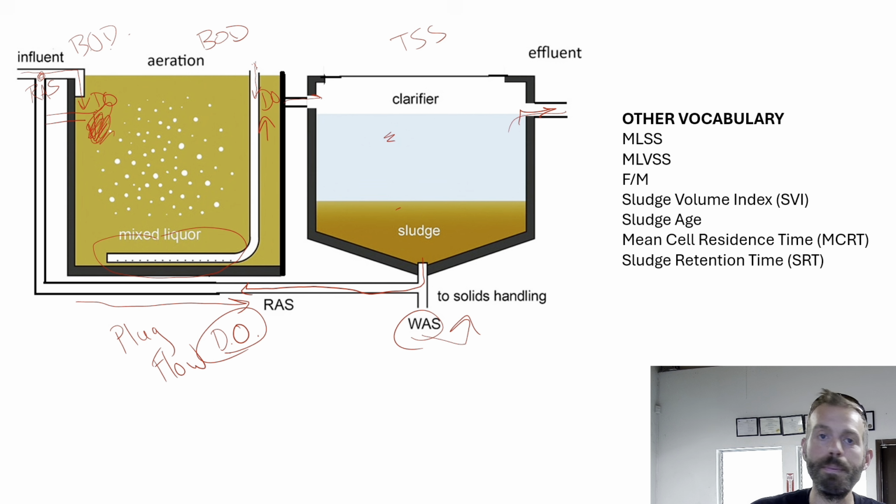Of course, pH, temperature, all these things, RAS rate, they're all important, but I would say the operator's two biggest tools are dissolved oxygen and WAS. I have seen some operators try to resolve problems with the RAS by turning it up or turning it down. That is not a long-term solution. Sure, in the short term, you took your ibuprofen for your headache, okay, but if you've not fixed the underlying problem, the headache might return, okay?